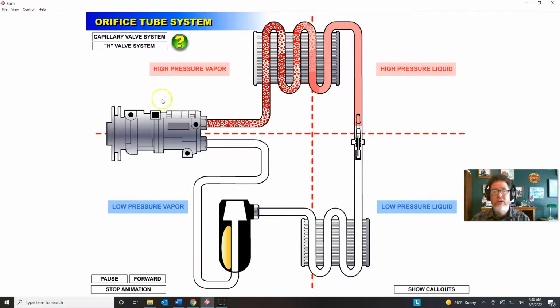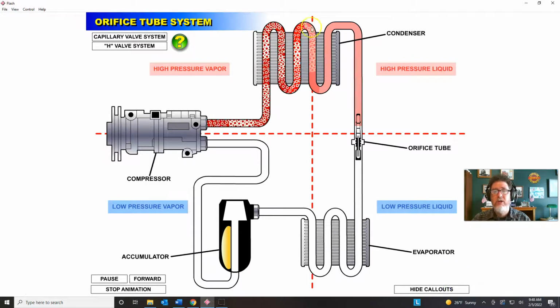And so then it's like, hey, is the compressor coming apart on you? Is all that Teflon coating on the pistons coming off? Is there metal on that screen? Did somebody replace the compressor and not change the condenser? We'll show the callouts here. And so at that point, the condenser, some debris from the previous repair got knocked loose, and then we're plugging up that orifice tube again. So you're going to want to look at the history of the repair to see if someone's been replacing one compressor, two compressors, and again, not doing a back flush or not replacing that condenser.